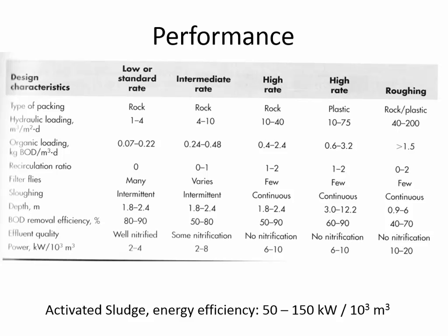If it has some certain diameter, then the filter area is going to be pi d squared divided by 4, with units of square meters. So the hydraulic loading rate is going to be Q divided by A. And that's where the units of cubic meters per day per square meter come from in the hydraulic loading rate.